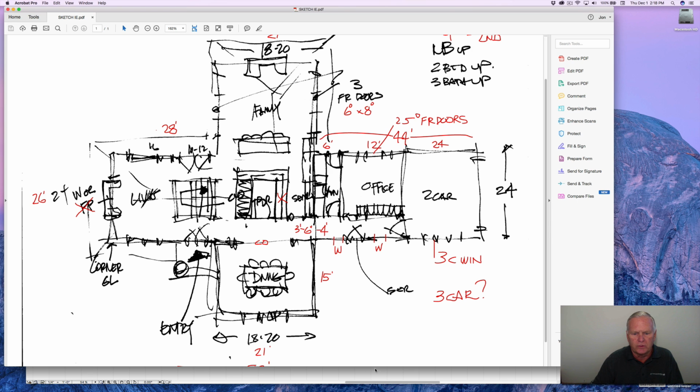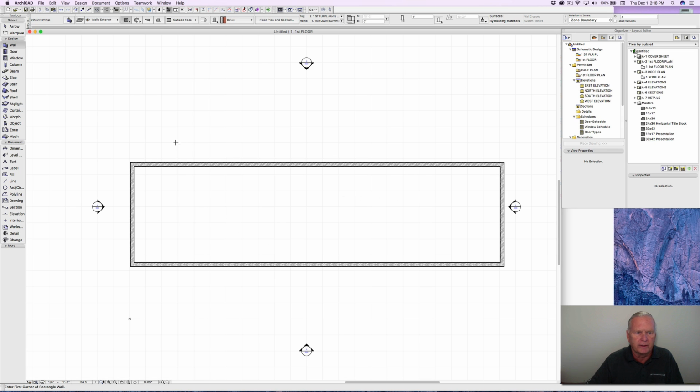Okay? So click back here, and the first thing we're going to do is hover over the end of this wall here, and you're going to see a little dot come up. And when we go over the dot, it turns into a guideline. We click down on it, hold it, drag it to the right, hit the letter D on our keyboard, and that locks it into a drag situation. That means our mouse can kind of float freely here.